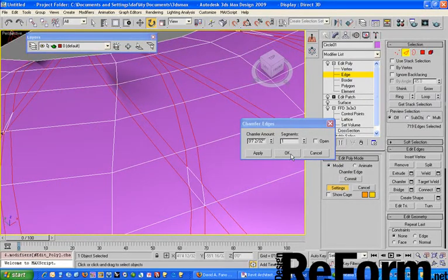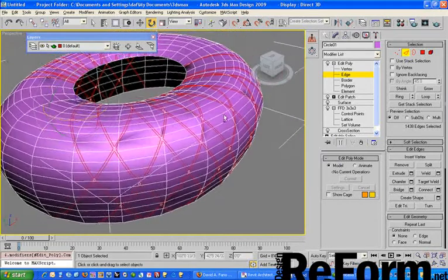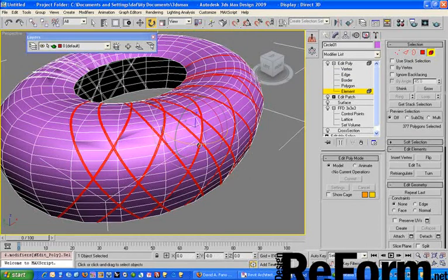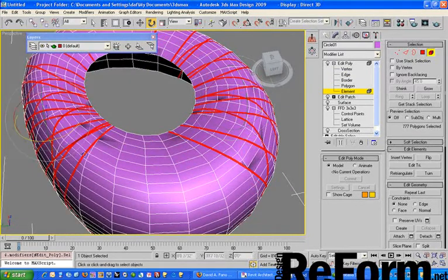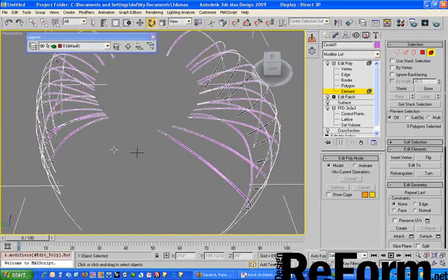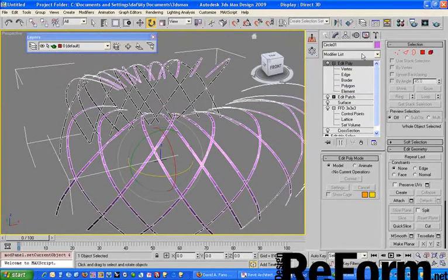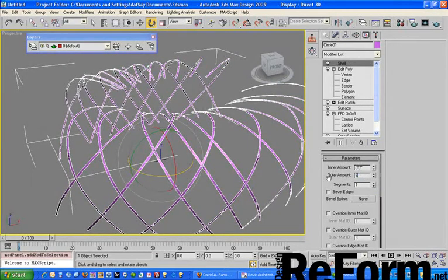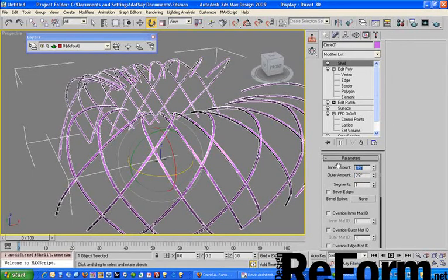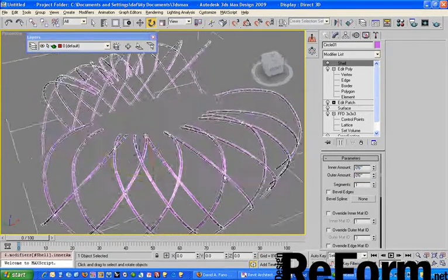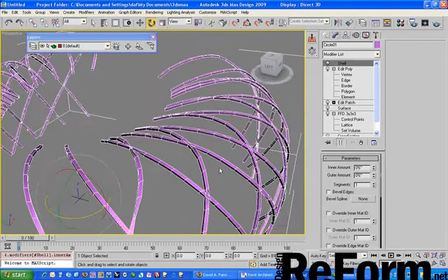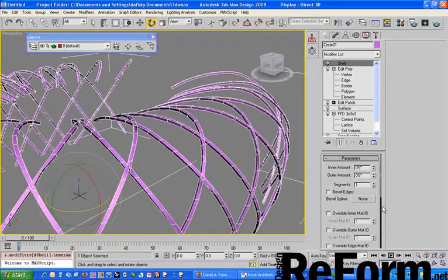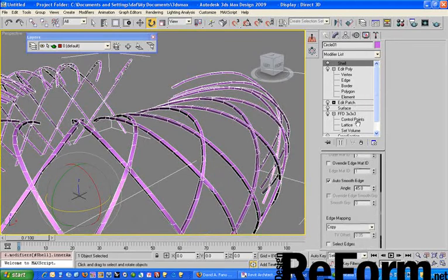We'll just take it through. Okay. And then split those faces, which we could then select these elements, do a Control I to invert, delete those, and we have these ribbons now. And if we shell these ribbons, we have these shapes. Which, I mean, we could globally do the procedures to turn them into I-beams or something like that if we needed them. That would be pretty easy, actually.